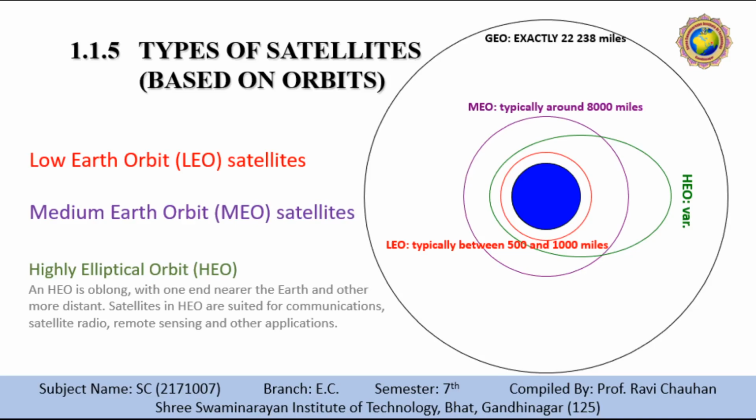The short time of visibility at high elevation requires an additional mechanism for connection handover between the different satellites. The high number of satellites combined with fast movements results in high complexity of the whole satellite system. One general problem of LEO is the short lifetime of about 5 to 8 years due to atmospheric drag and radiation from the inner Van Allen belt 1. Assuming 48 satellites and a lifetime of 8 years, new satellites would be needed every 2 months.